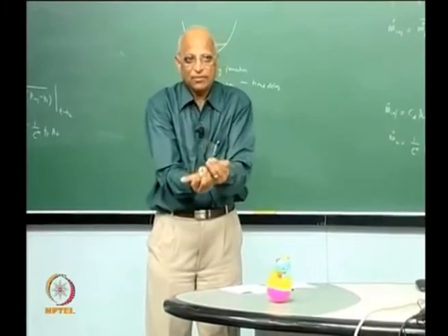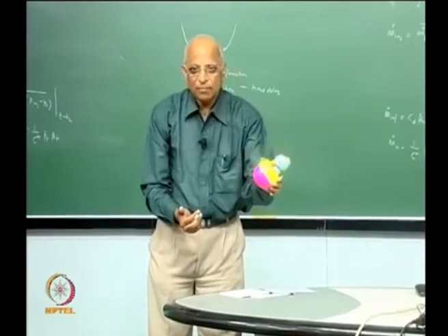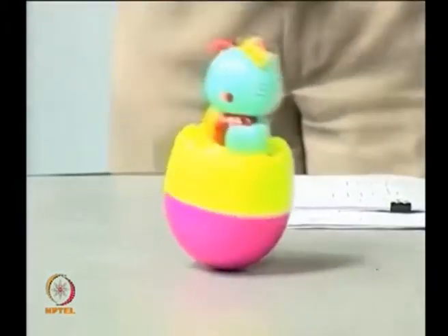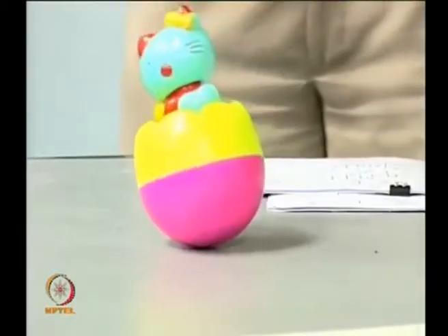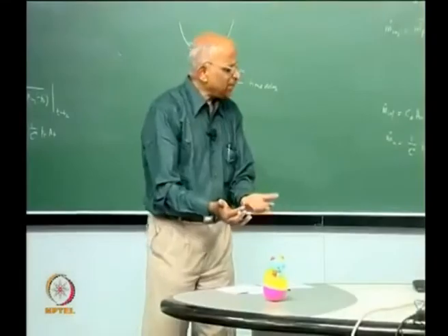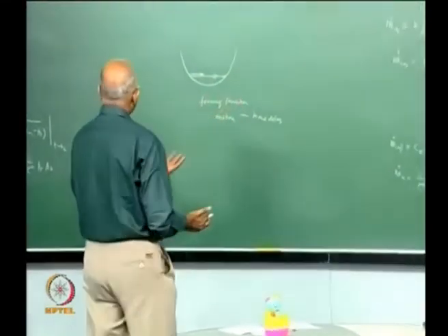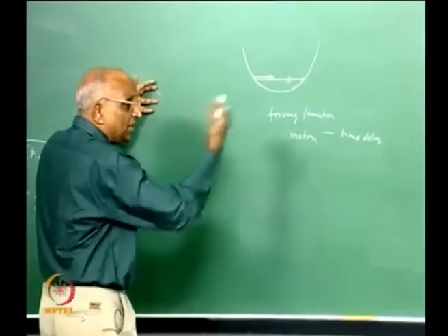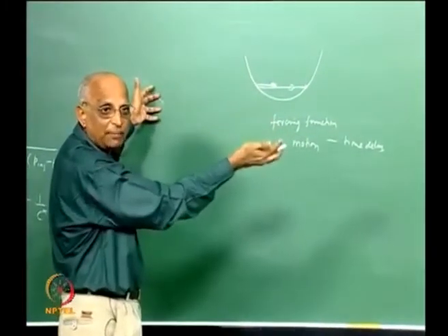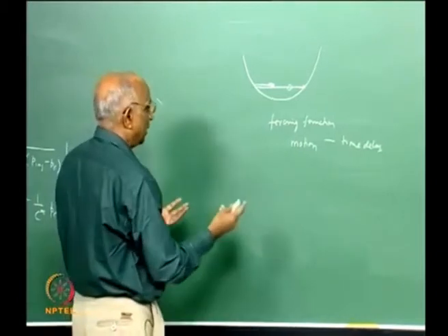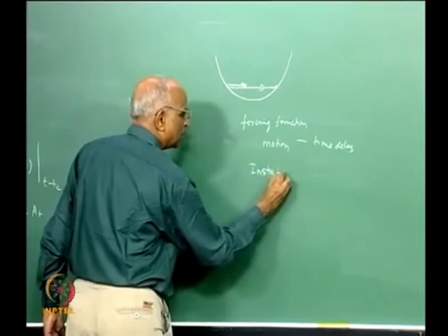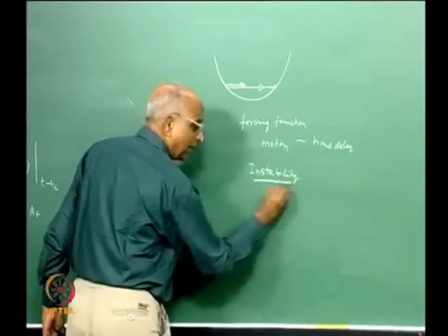Sometimes because of center of gravity you do, but in this case there is a marble inside, and it is this which keeps it going up and down, and the friction essentially stops it. It is exactly the same thing that is happening here. You inject propellants, there is a time delay, the time delay precedes whatever change happens, and this is what happens in one case of instability.